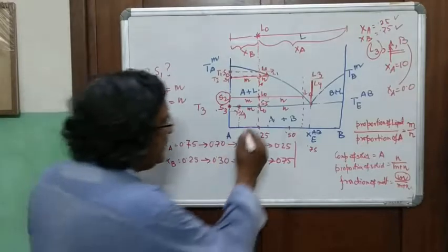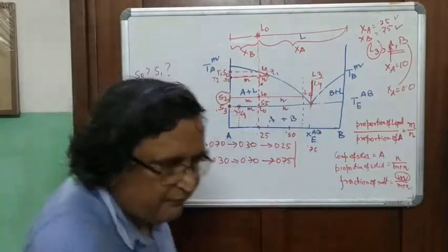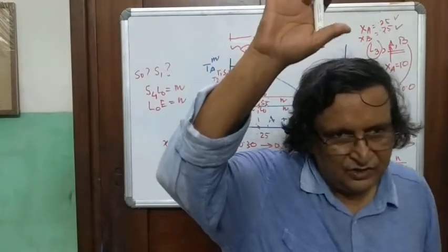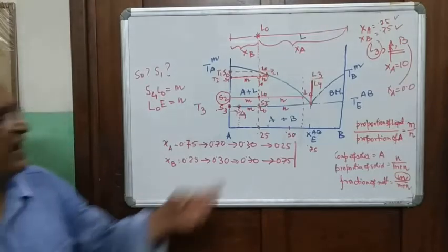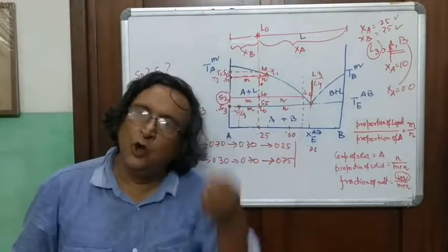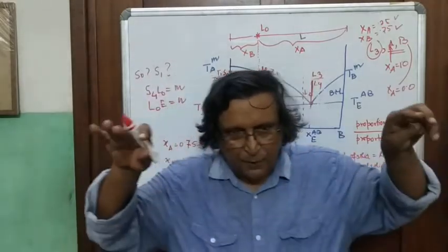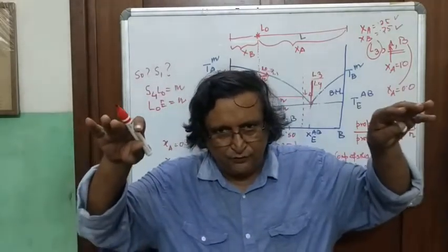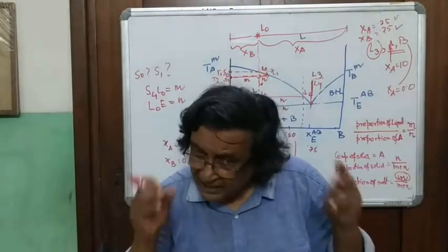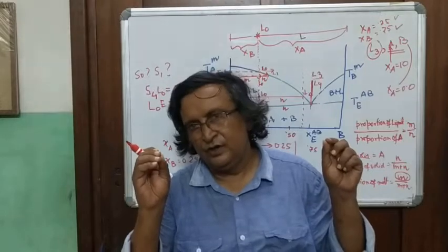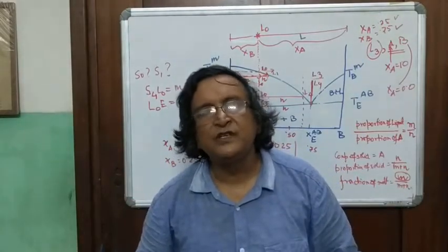So, the final solid, and this will be the last melt here, will exhaust. The last melt will exhaust, because there cannot be any more melt, because the whole melt has solidified. At the eutectic, the melt in the proportion AB at 0.75, 0.25 precipitated A and B in the same proportion as pure solids. But at one point of time, you had to exhaust.